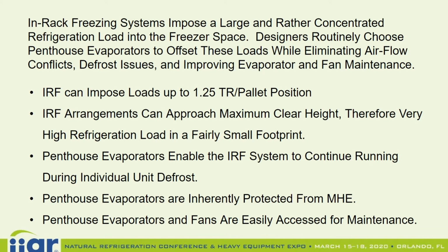But when you look at the concentration of load, an in-rack freezing pallet position can impose loads of up to 1.25 tons per pallet position. And when you look at the ability for the in-rack freezing systems to follow the height of the building, we're able to have a very high concentration of pallet positions in a very small footprint of the facility.